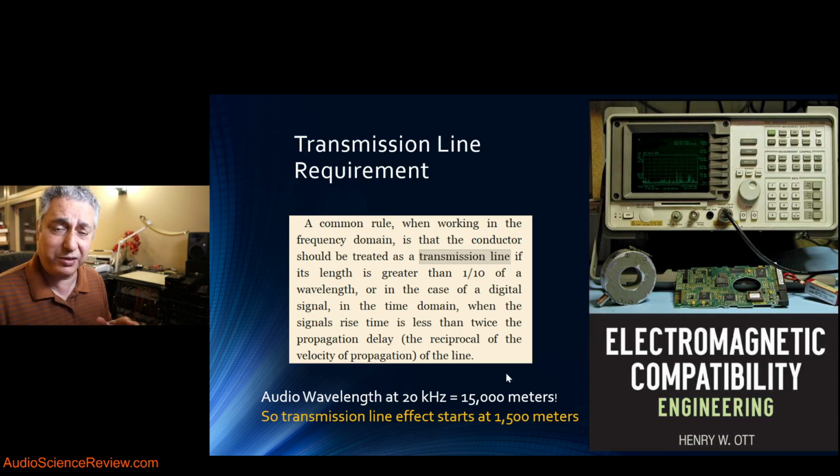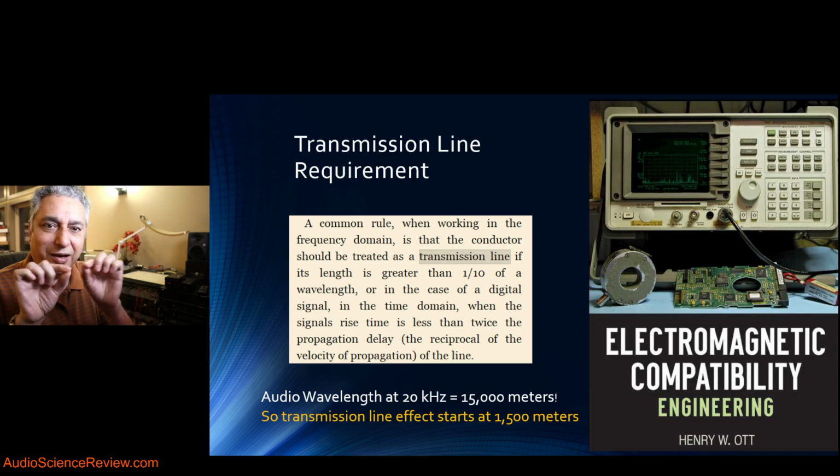And that's a great thing, because if you open up an audio amplifier or audio DAC, it has nothing in there that is designed based on these principles. Whereas if you open an FM transmitter or your cell phone, the RF section of that, you'll see all kinds of tricks in how even the smallest line or PC board trace is meticulously designed and drawn. And if you just touch that trace, everything stops working. Whereas I can touch an audio amplifier inside, and nothing will happen. It'll just work just as well as it did before.